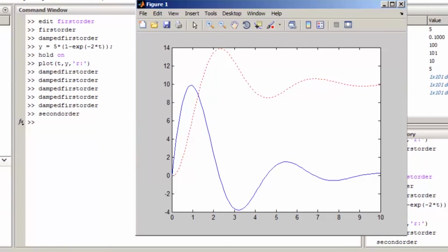This seems to make sense. A spring mass damper system can oscillate, and the final value of both velocity and position makes sense. The final position is 10 meters, which is the same as the applied force divided by the spring rate. So at the final position, the spring force counterbalances the applied force. The final velocity is 0, since with a constant force, the system should come to a rest.